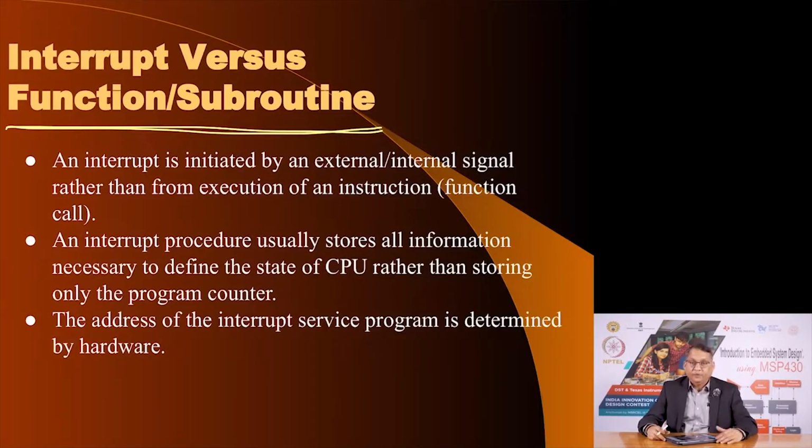Also, you need to know, for a given interrupt, where the subroutine is, because there may be several sources of interrupts and you cannot go to a single address to find out who generated that interrupt. The way it is handled is that for all the various sources of interrupts, you associate a unique address where you put your subroutine, which would be executed when such an interrupt happens. So, that is this aspect.